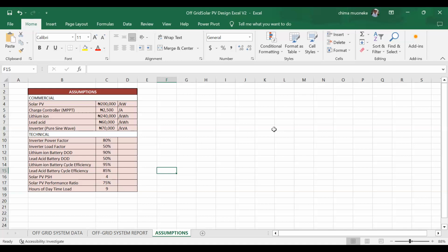So we look at the number of cycles. When you look at the technical data sheet of this battery, you're going to see the number of cycles that the battery will last. For typical lithium-ion batteries, it's usually about 6,000 cycles. That means the battery will charge fully and discharge fully 6,000 times, and then the battery will be considered to have degraded. Not degraded to 0%, but to maybe about 80% or 70%. So that's the way we look at it.